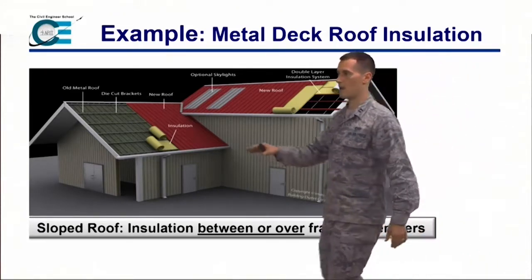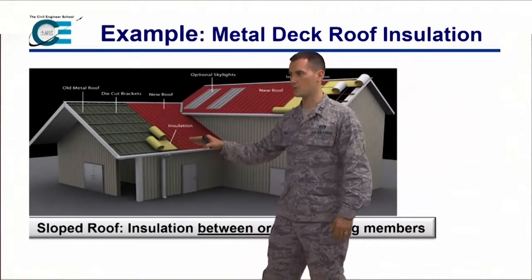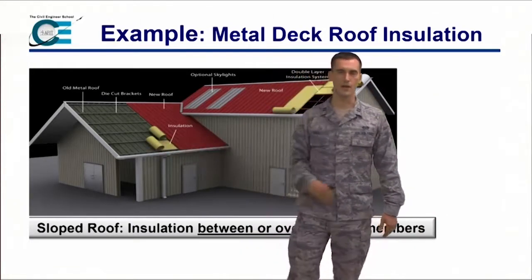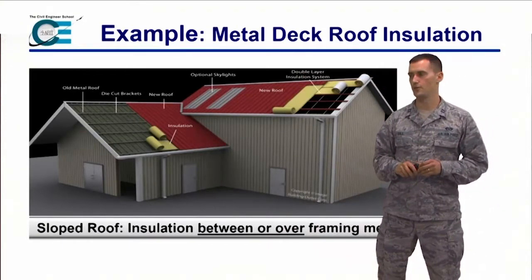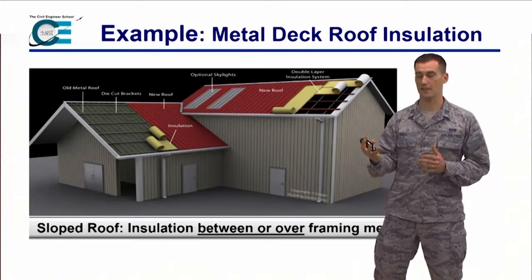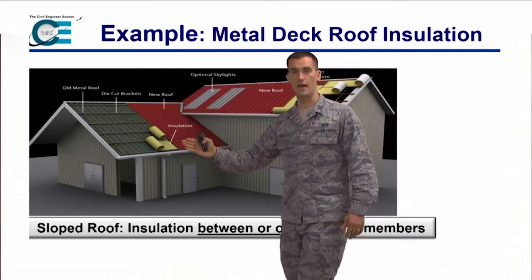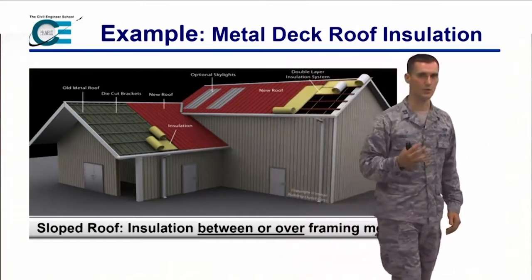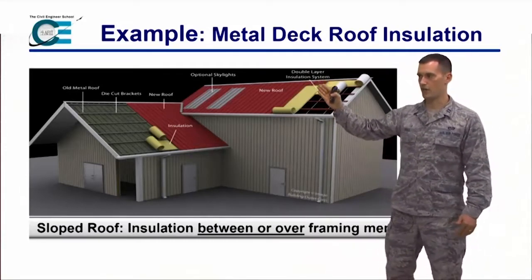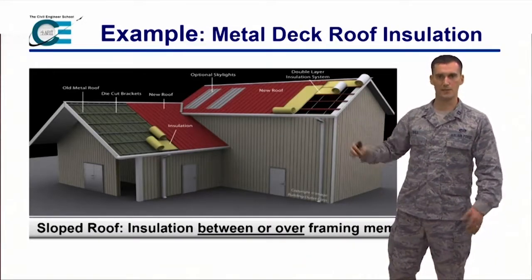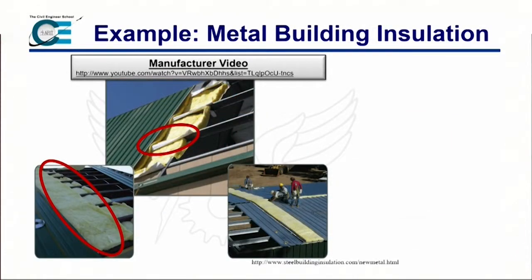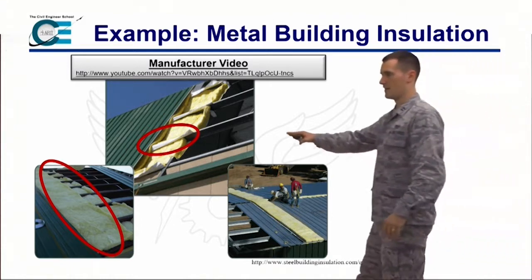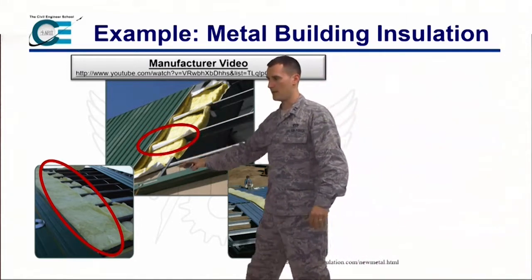So the same way here, if I just have an exposed metal or wood stud, energy is going to follow the path of least resistance. It's a lot easier to go through that than it is to go through the insulation, and so I lose some of the energy there. So we want to cover up those as well, but constructability is a challenge, but there are solutions to that. So, for instance, as you can kind of see here, this gets sloppy and difficult to do.